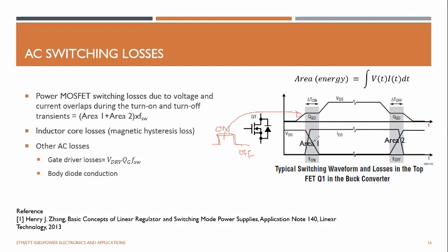This average voltage here is VDS divided by 2. This is the average voltage across here, I'm talking about this value. And the average current is IDS divided by 2. This is that average current.